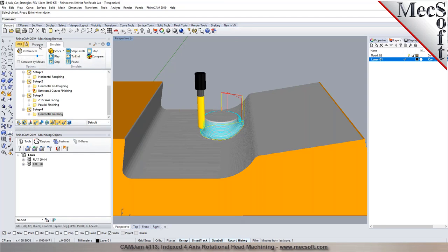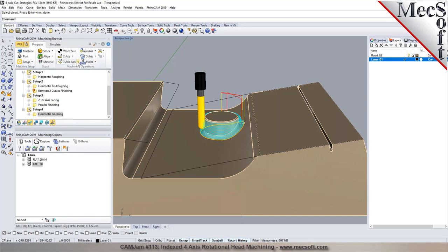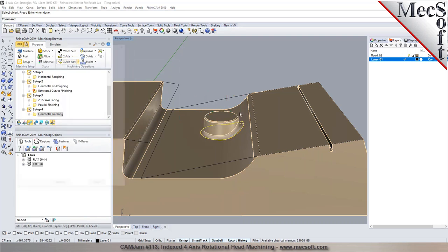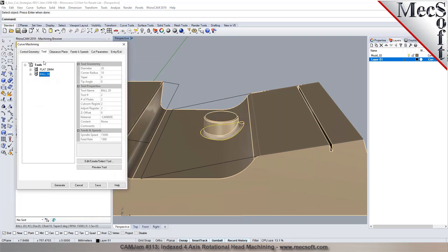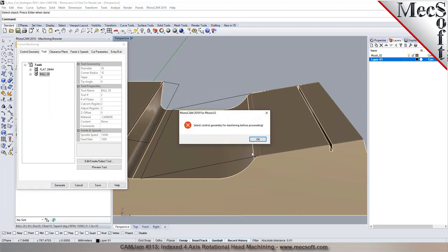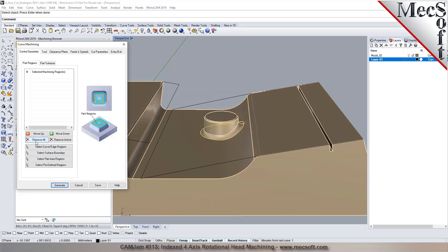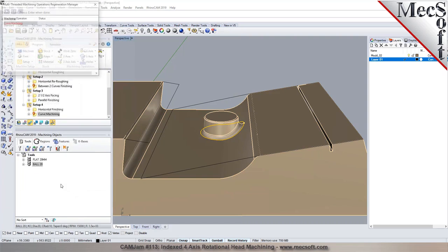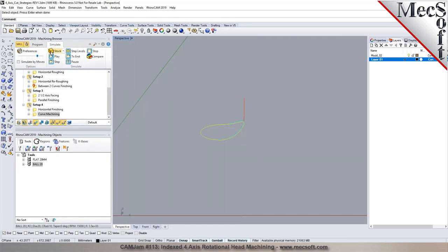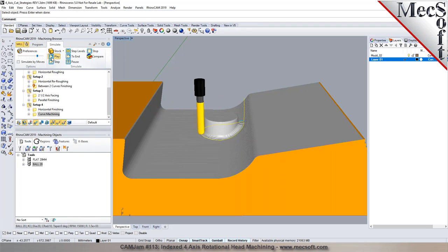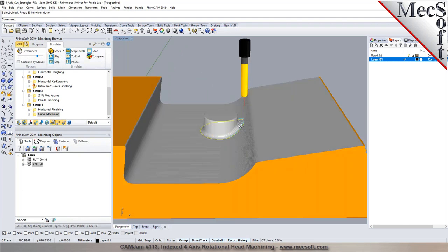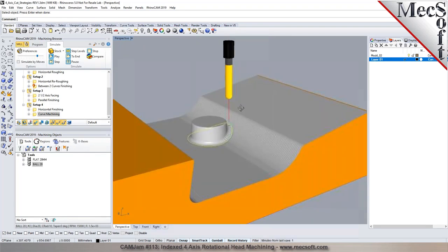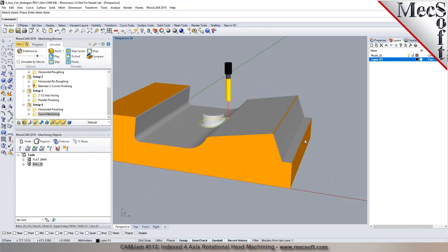And you can go back and clean this up with a 3-axis operation like a curve machining. So just to go around to clean it up. Just go around the edge. Yep. So it's select my control geometry. So I'm just going to go pick this here. And if the radius is matching exactly what you have, it will just give you one nice pass to go clean it up. Yep. Or if you want to do additional passes, we can step it over as well. Yep. That demonstrates.